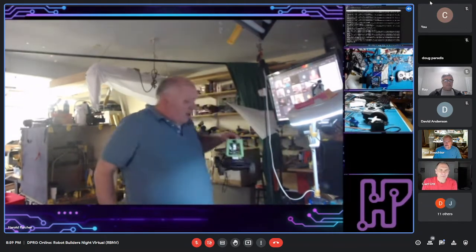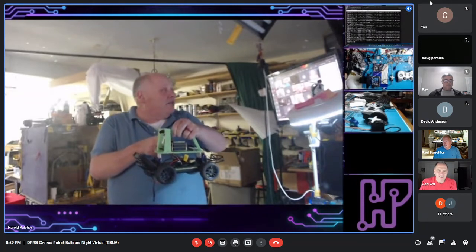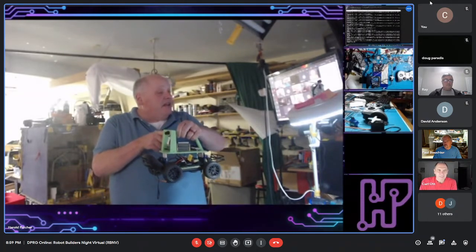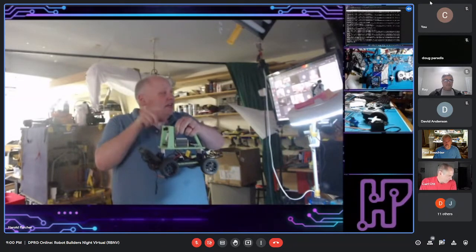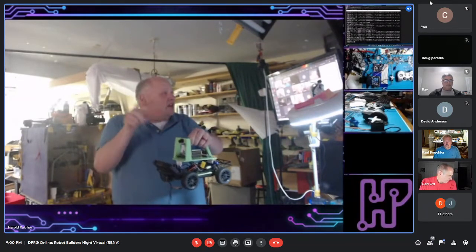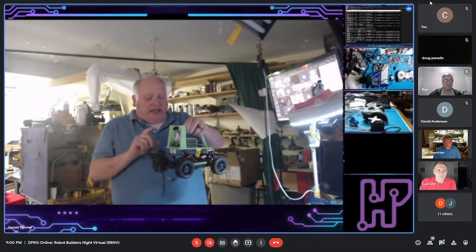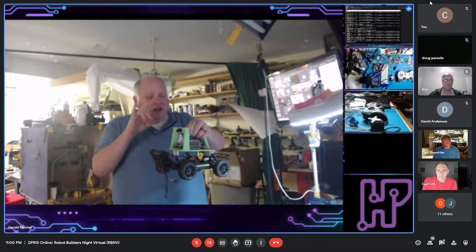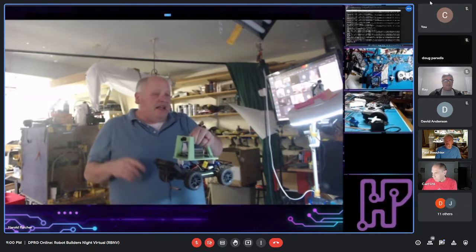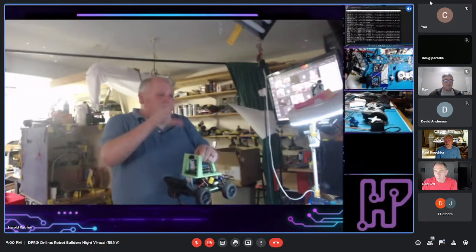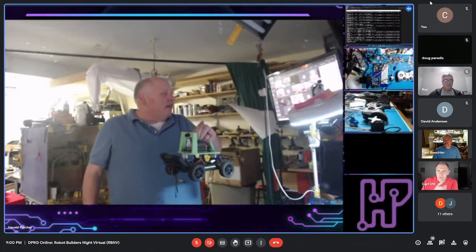is a donkey car, right? Oh, that's a Raspberry Pi on it too. And guess what? I should be able to copy all this stuff, put it in its own repo, fire up the container on this, configure the nodes, because at this point I only need a driving node, a steering node. I only need basically two servo nodes, one for the speed control and one for the steering. And then it could be that I reconfigure just what I've done here and make this thing work. Could be. In short order.